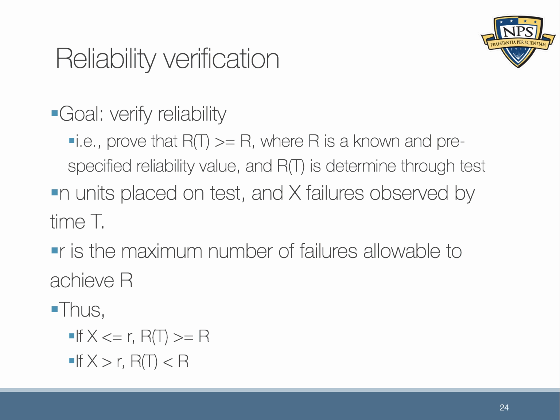So 1 minus reliability of a particular failure mode, right? So I mentioned this idea earlier of a supplier that had a dull saw and it was causing delamination of one of our electrical components, right? So we could prove out the reliability of that particular failure using this method. So it's just generically called reliability verification.